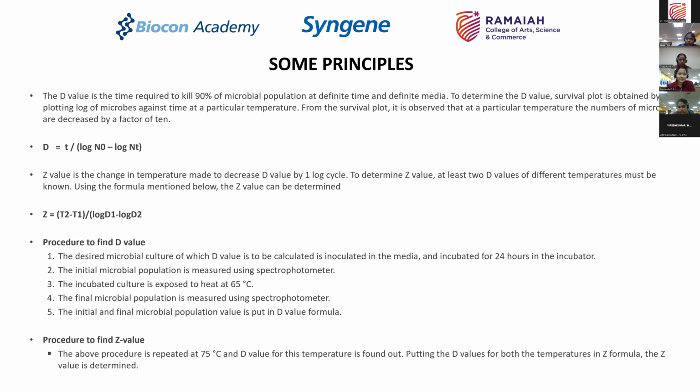Sir, can you explain the Z value again? Sir, how to plot the graph of Z value? Okay. So what you will do for determining the Z value is that what is Z value? Z value is the change in the temperature which will make the D value change by 1 log reduction, right?